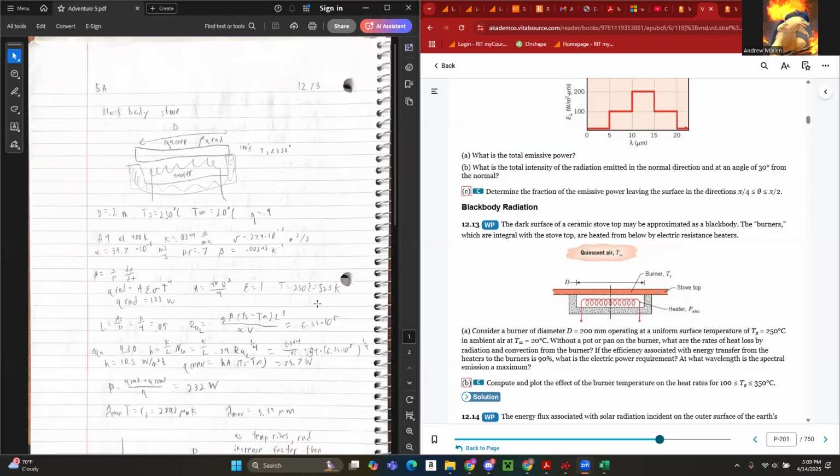Now in order to find h, we need to know k and L. h is just equal to the thermal conductivity over the characteristic length times the Nusselt number. In this case, the Nusselt number is equal to 0.45 times the Rayleigh number to the 1/4 power. This is obtained from equation 9.30, which details convection on the far side of a heated plate.